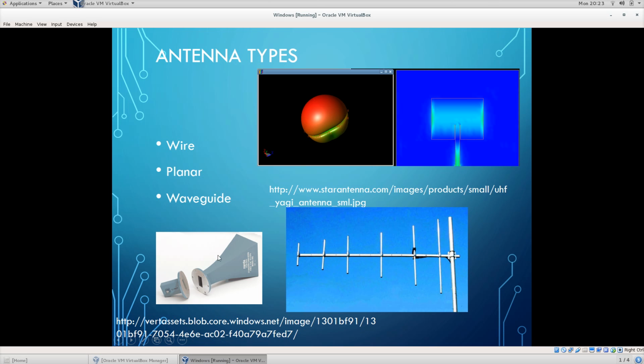This is a waveguide antenna. Now, waveguide antennas are a little interesting because waveguides can actually radiate all sorts of frequencies above their cutoff. The same applies with waveguide antennas as a whole. However, they get worse and worse as you get outside of their dimensional band of operation. One of the antennas that we're using in class is actually an AH-118 broadband horn. When we get into class, you'll be able to see it has some really interesting structure. It's called a dual-ridged horn, and it's got a lot of extra stuff in there to allow it to operate over a much wider bandwidth.